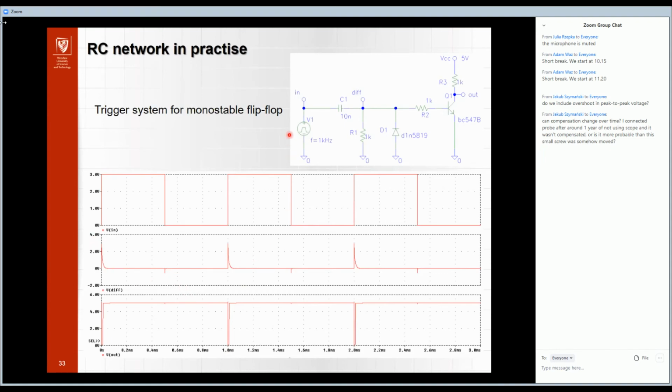And of course, these pulses should be symmetric, but they are not symmetrical in this system because we have the diode here, and the diode shorts these pulses, and we see only the voltage which is typically across a diode that is on.